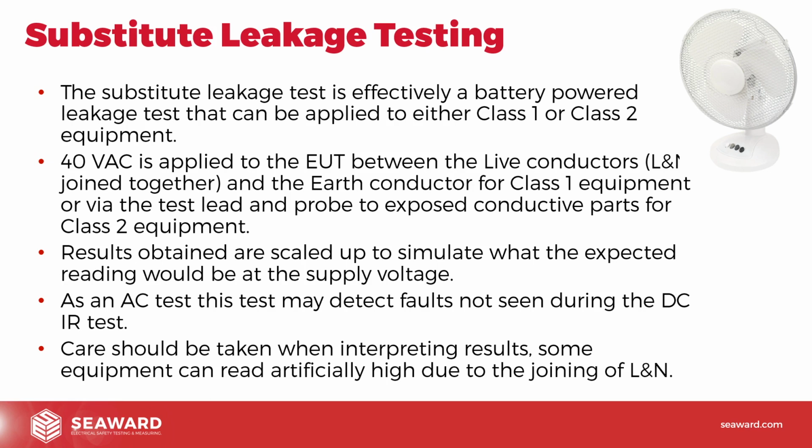It's a great test because it's something we can actually apply. It's battery powered. It's a very soft, safe test, so you don't need mains to carry out the test. It's also not going to damage equipment. It's not going to actually turn it on and spin it round and all those sort of dangerous things. So where we were talking about checking to the drill chuck, for example, a substitute leakage test would be a good option in that case, because it's not actually going to spin the drill chuck round, so we can do a measurement to it.